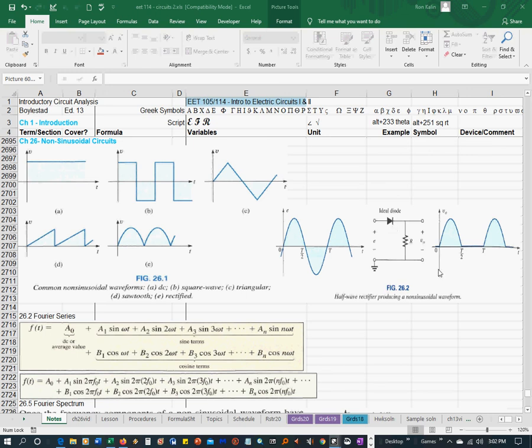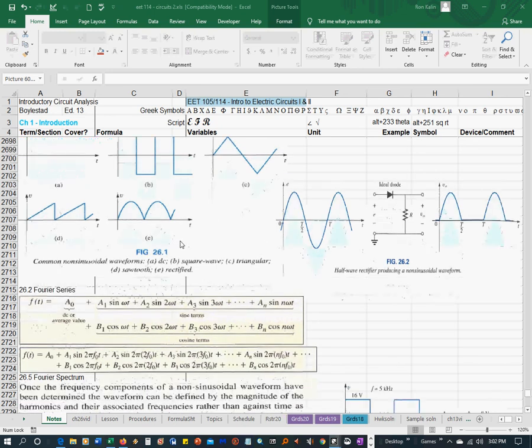Anyways, when you look at the current coming in and the current coming out, the current in looks like a regular sinusoid and the current out looks like this, which is half wave rectified. So it's only allowing the positive to go through here. When it goes in this direction, it allows it to go through. When it goes back the other way, it doesn't allow any current flow and it's just flat. So it's clipped. Those are examples of what they look like.